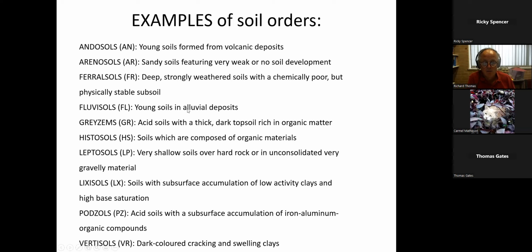This is like talking about alluvial deposits. Fluvisols come from redeposition of material formed one place and deposited somewhere else. I'm not going to go through the whole list, but what you will see they all have in common is that they are iron aluminium silicates. Okay, and then we've got the vertisols, these clays, and clays are very, very fine particles of soil that are broken down, that then get a particular structure to them that allows them to take in huge amounts of water and huge amounts of other metal ions into them. They soak up and swell and shrink.